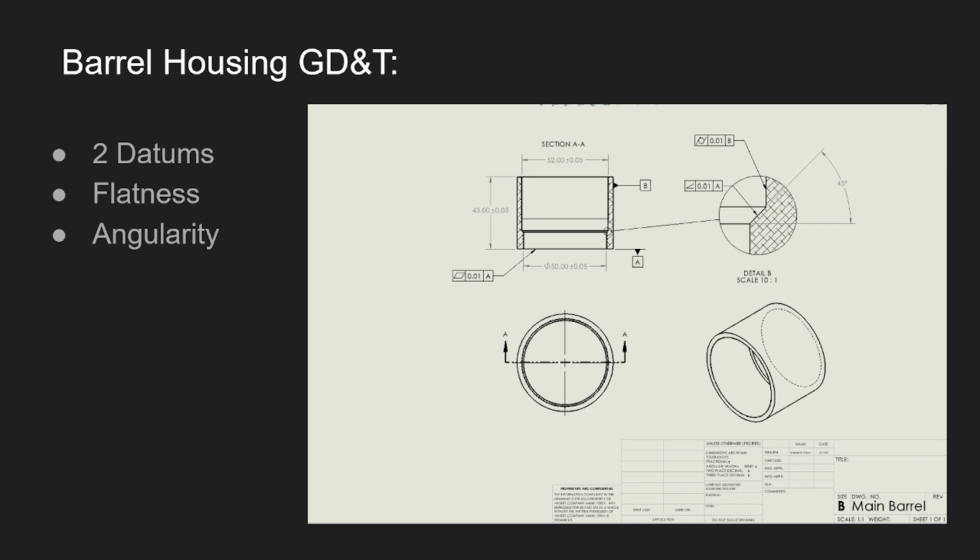In the first drawing of the main barrel of the lens, there are a total of two datums that are perpendicular to each other and act as a reference for geometric control during manufacturing. Datum A is defined as a flat plane on the bottom of the barrel, with it placed upright. This is critical because it serves as the primary reference for orientation. It ensures the entire assembly is seated flat and level during both manufacturing and final inspection.